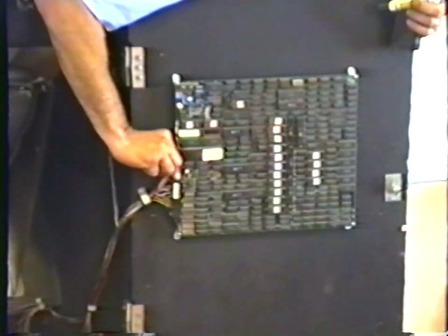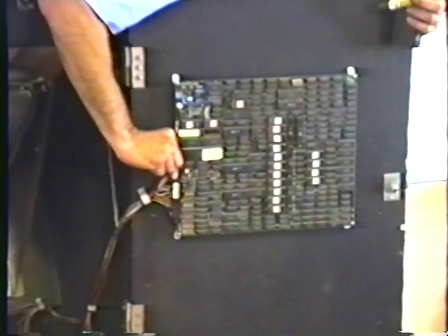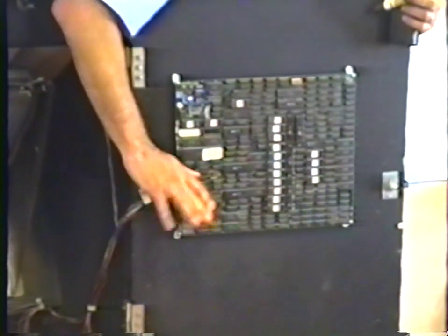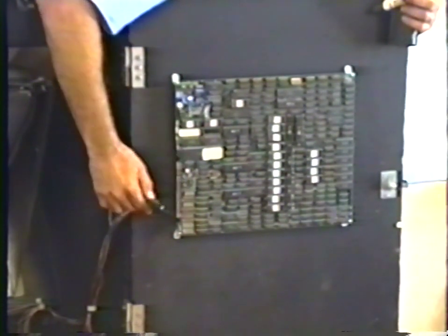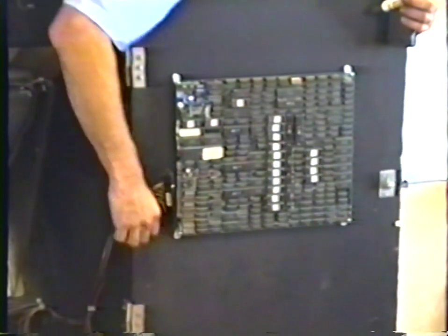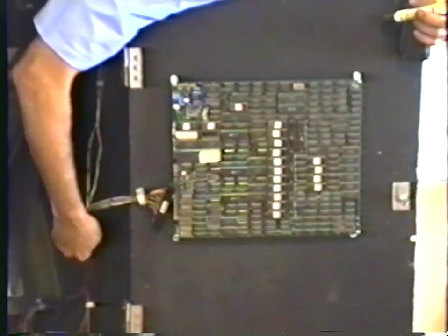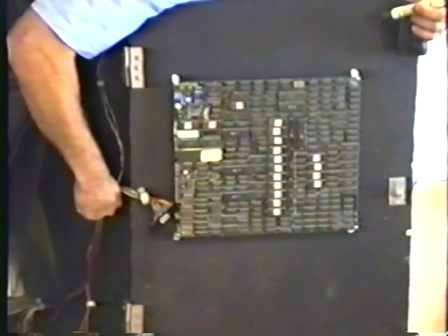If you can move the connector like this and the game freaks out and goes on and off, if you move the connector back and forth, the game freaks out, you probably have some bad pins on the connector. Like this one just doesn't hold on worth anything. Part of that is the terrible way that this was mounted in here. Too tight. Just too tight.